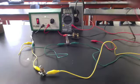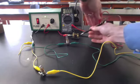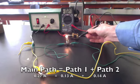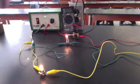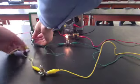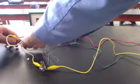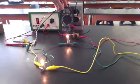The current on the main path, that's both path 1 and path 2, is 0.27 amps. Notice 0.13 plus 0.14 is 0.27. The current through the main path before the split was the two currents on each path added together. And that is the same as the main path going back to the power supply. This is also reading 0.27 amps.